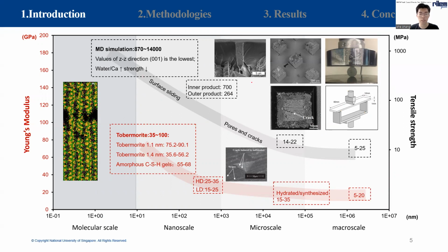These defects act as stress concentrators, leading to local stress concentrations and the initiation and the propagation of cracks at lower applied stress levels. As a result, the material exhibits lower strength when tested at larger dimensions. This effect is significant when testing modulus and tensile strength from the previous results.